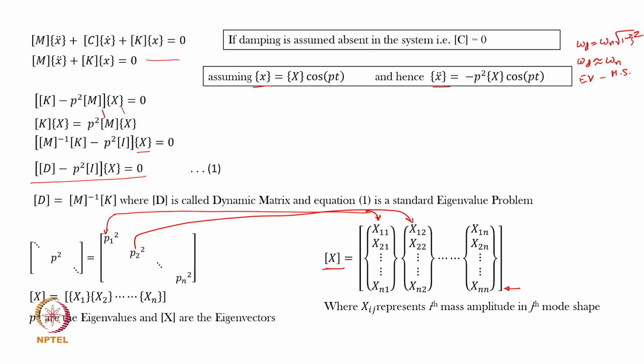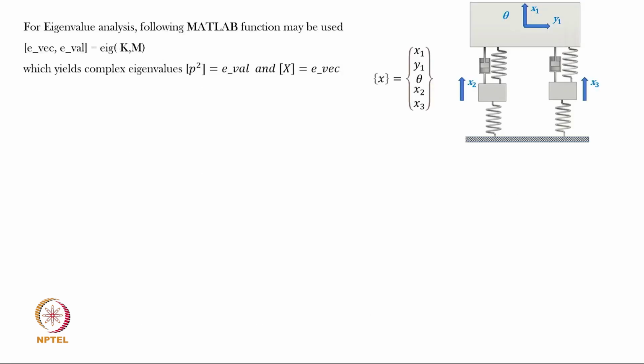So, this is how a multi-degree of freedom system gets formulated as a matrix equation. It becomes more appropriate to represent them in the form of matrices. Each individual matrix will have elements depending upon the parameters of the vibratory system, like the masses and the stiffnesses of different elements. Now, as I mentioned to you, you can use numeric methods, you can have your own function written in any of the languages.